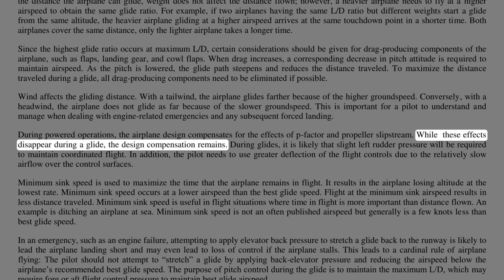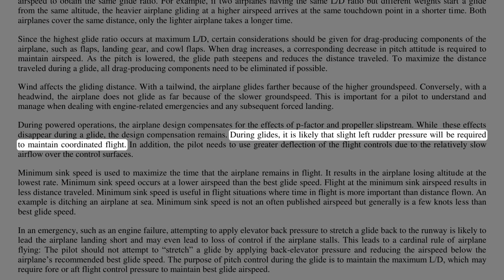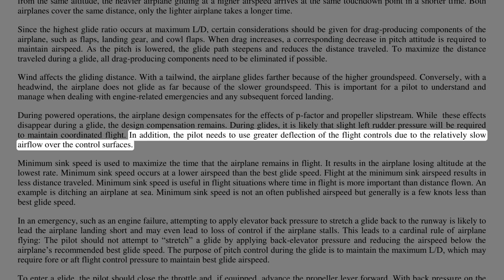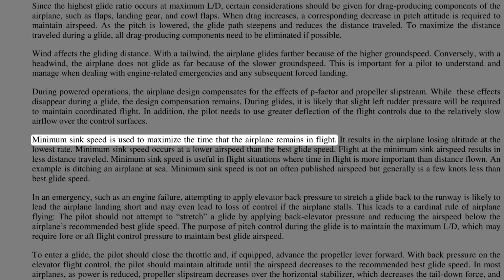While these effects disappear during a glide, the design compensation remains. During glides, it is likely that slight left rudder pressure will be required to maintain coordinated flight. In addition, the pilot needs to use greater deflection of the flight controls due to the relatively slow airflow over the control surfaces.